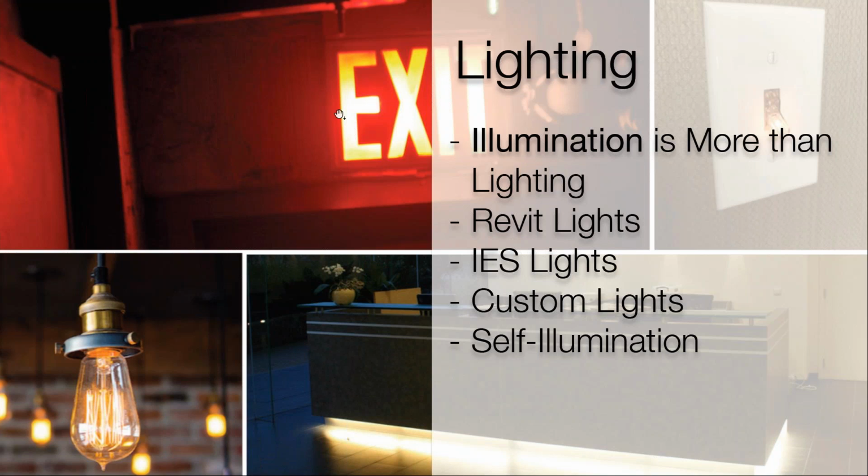Or think about an exit sign. Exit signs do not schedule in Revit as lights. You don't want to nest light objects inside of them to get them to appear to glow in a low light condition when you're trying to visualize a life safety egress study. Or think about a reception desk. That kind of accent lighting would be very, very tedious to create by nesting Revit light objects, but you still need to create the appearance of illumination. And this is really easily done with a material editor.